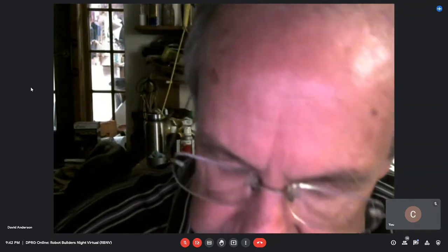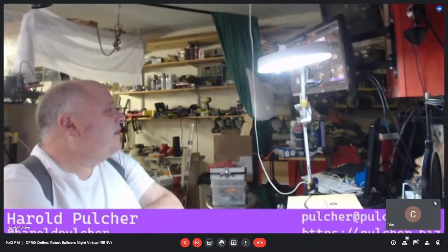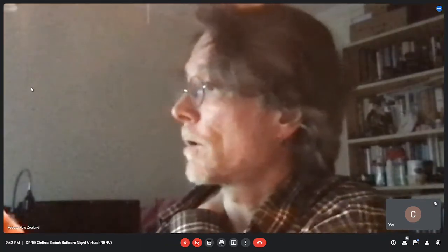Also noticed that the BNO055 has the data and clock signals. It's got power and ground, and it's got a reset signal. Any of you who've used this, do you use that reset signal? You don't need it. I don't think you're going to need it. I think it's to recalibrate itself when you're doing the thing. Okay, there's a VIN, and then there's also 3.3 volts. Is that an output? The VIN is your voltage. Yeah, it actually has an onboard 3.3 volt regulator. That's an output. But honestly, either to me directly or in the mailing list, tell us which model it is,